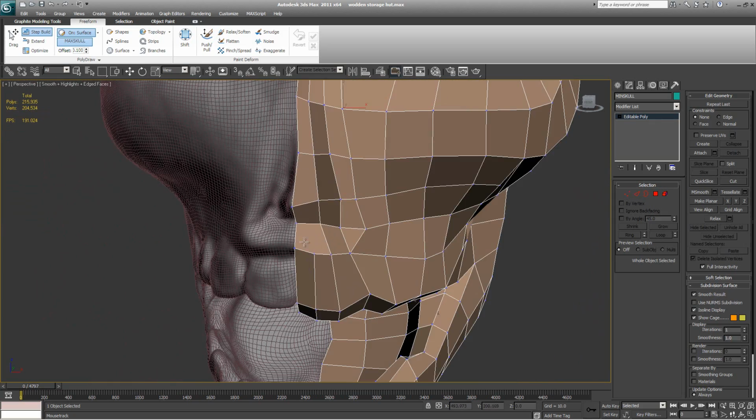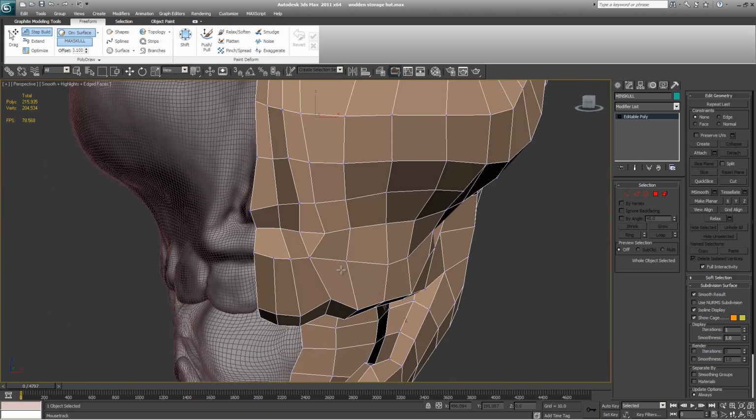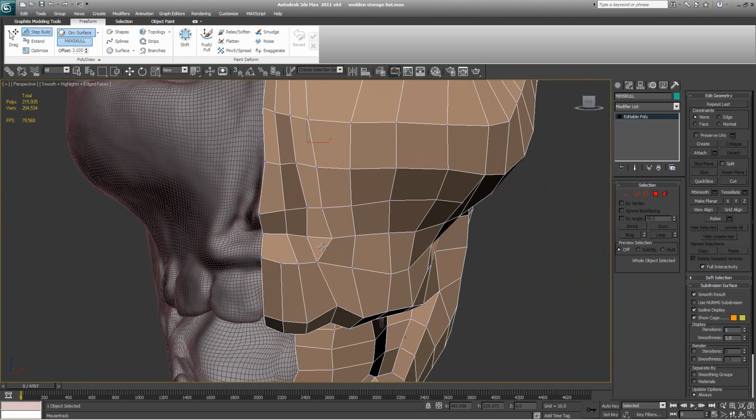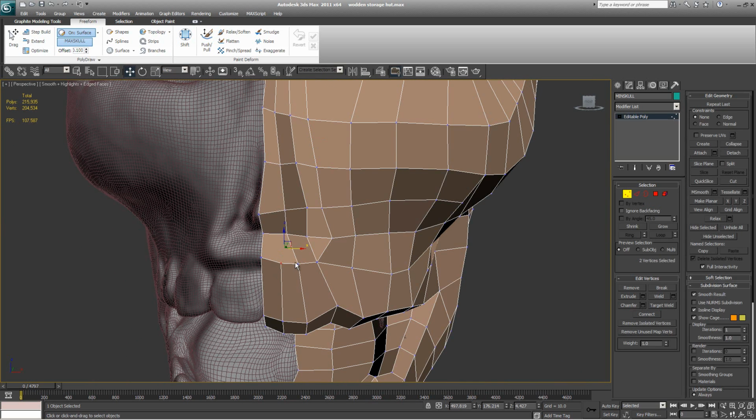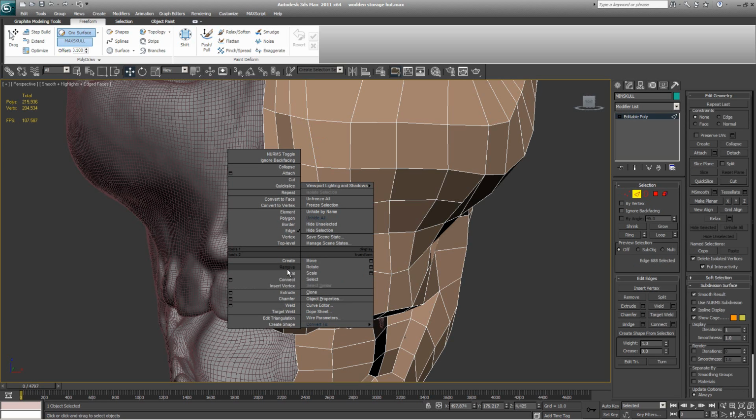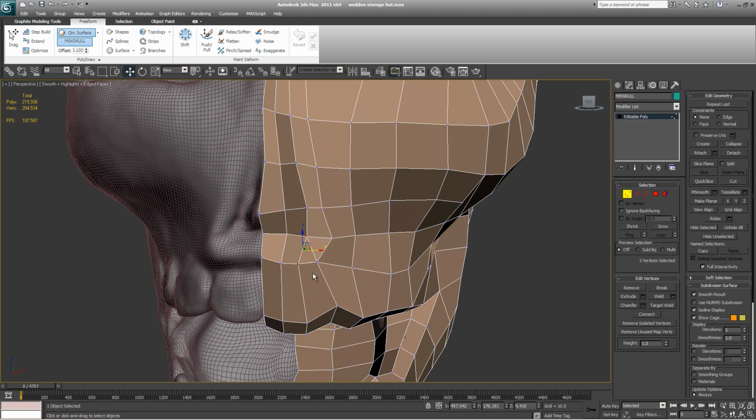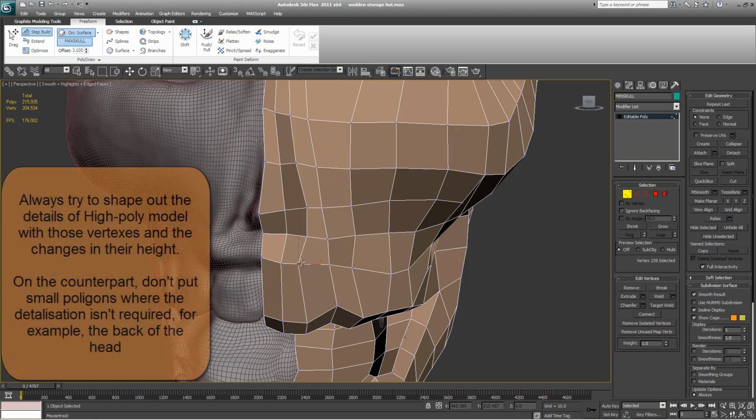You see that there is a pentagon and a triangle over here, and the way to fix it would be to get out of the step build by right-clicking somewhere on the scene, press 1 and connect those two vertices, remove this one, connect those two, and remove this one, and then go back into the step build, press Ctrl Alt and reposition your vertices to the desired position.